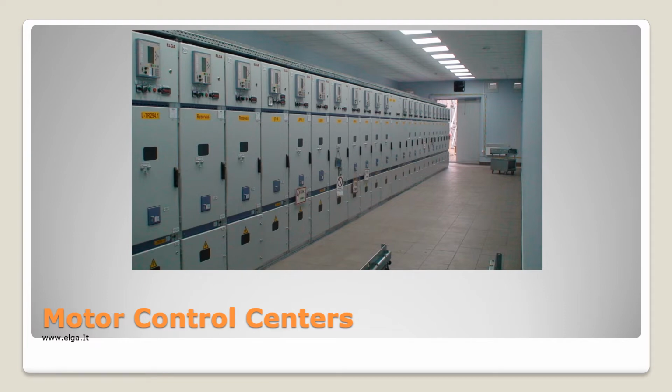Not all motor control centers are this big. We have motor control centers downstairs in this building, and those motor control centers are slightly smaller than these, but they all perform essentially the same thing. A motor control center is simply the place where power comes in through a protective device that you'll learn about later, and you'll actually put one together in lab.